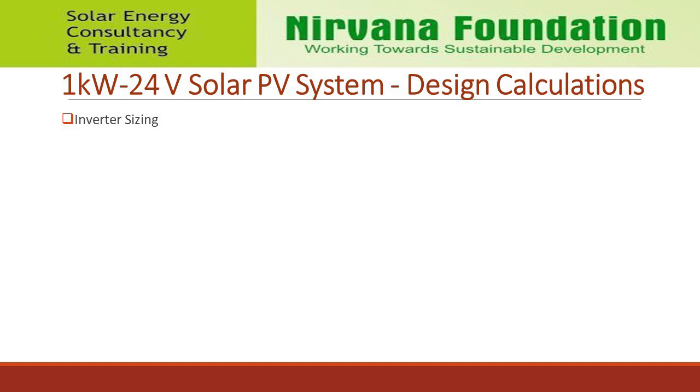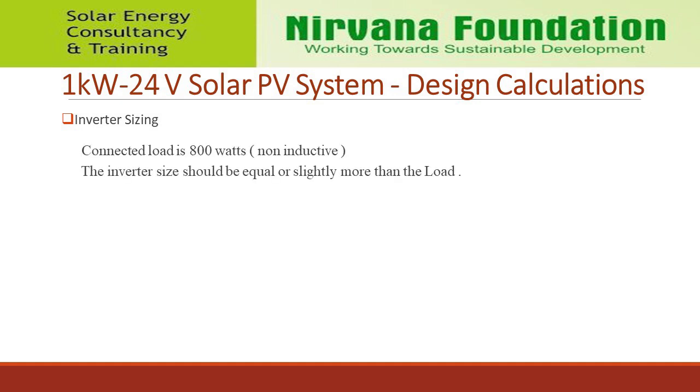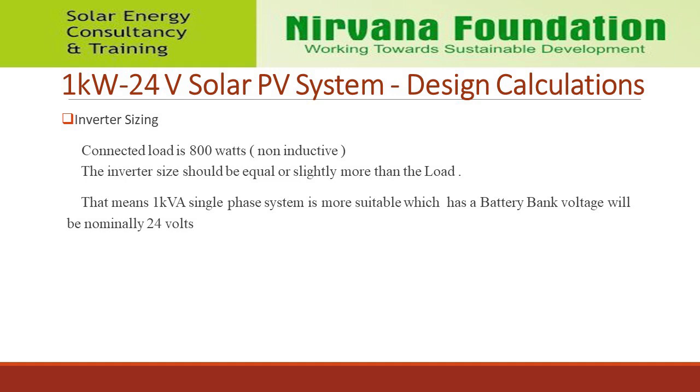Inverter sizing. Previously we have calculated total wattage of connected loads as 800 W. So the size of the inverter must be slightly more than the total load. We can select a 1 kVA rating inverter with a battery rating of 24 volts.